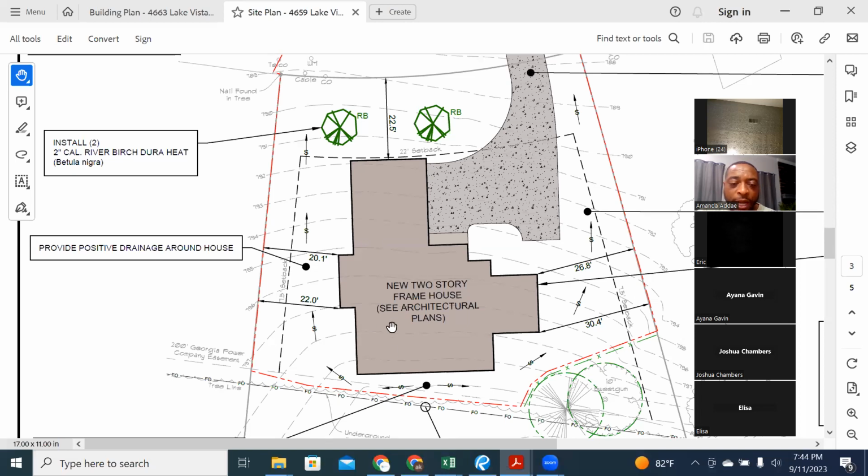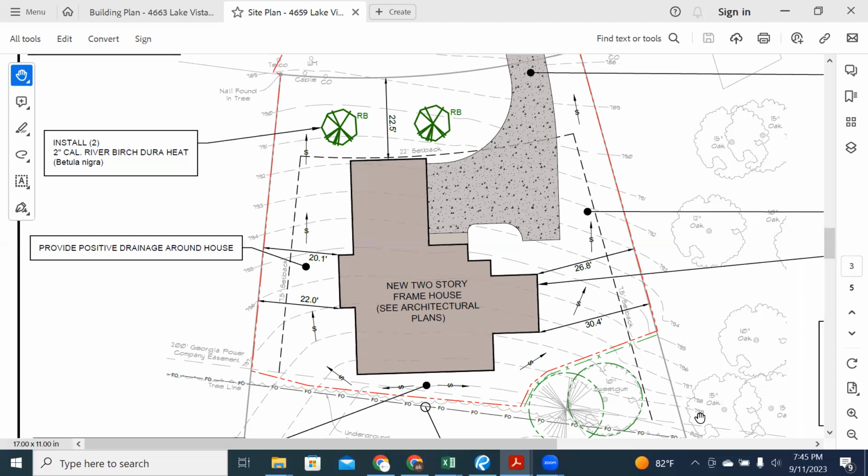So on this particular house, if y'all recall, we talked about how you find the elevation. Over here, our elevation is 797, 796, 797, that's 2 feet. By the time you get here, you're almost at 800. 799 over here, right here, that's what's back here.